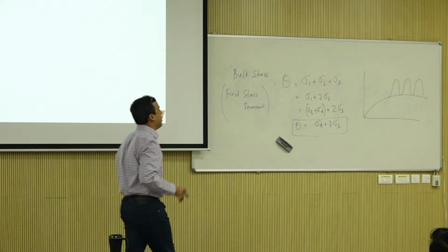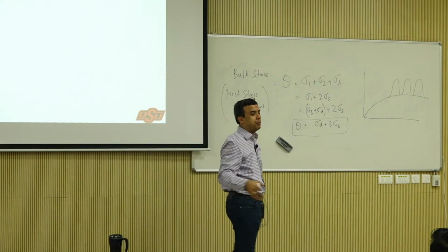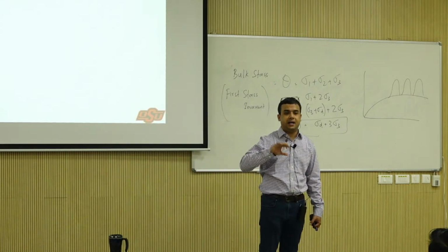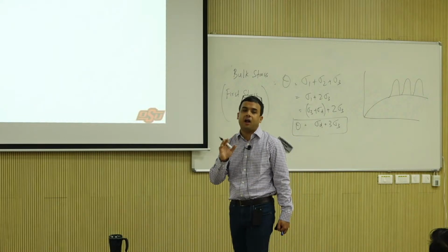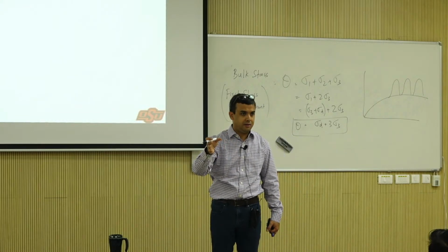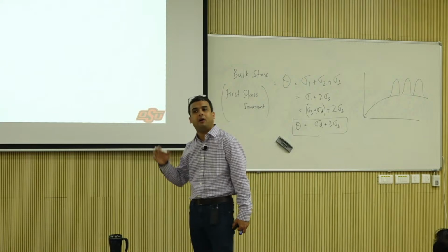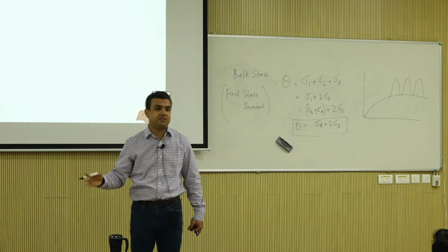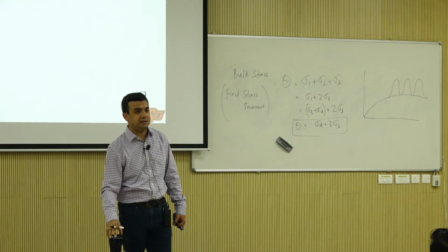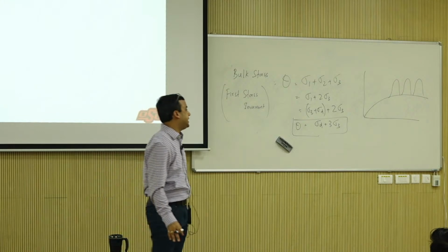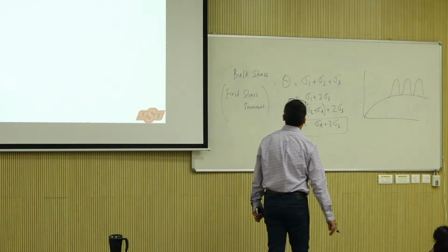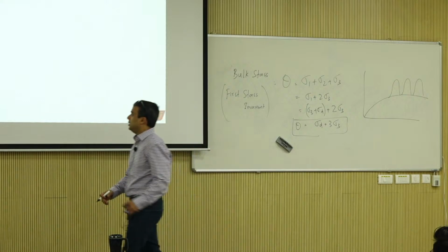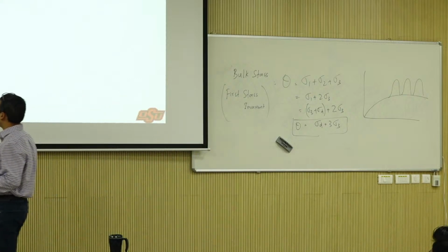The only difference is the permanent deformation test, which we will cover mostly tomorrow, among other things. They'll run for a lot longer. Permanent deformation tests are run under a million cycles, 10 million cycles, at least 10,000. The longest I have run for a paper was 10,000, not longer than that. And that gives you rutting.